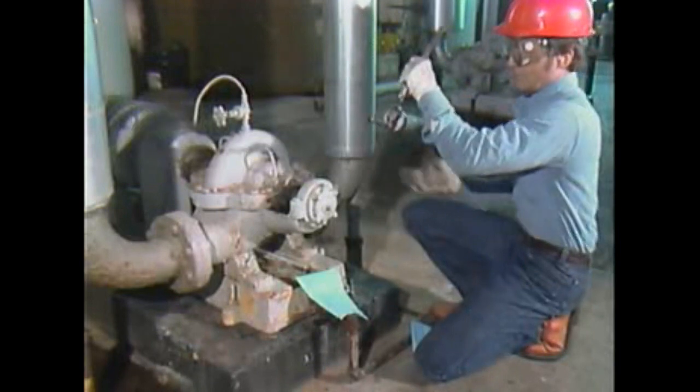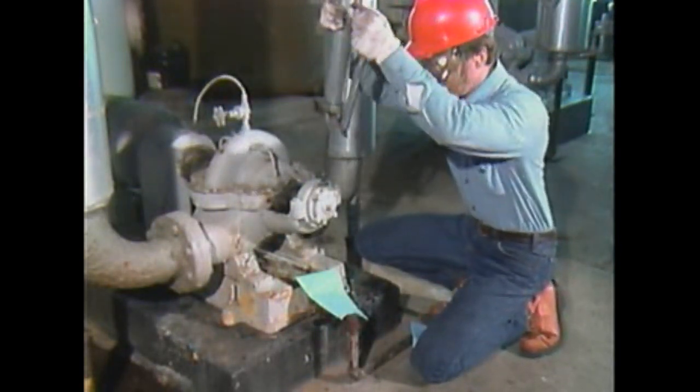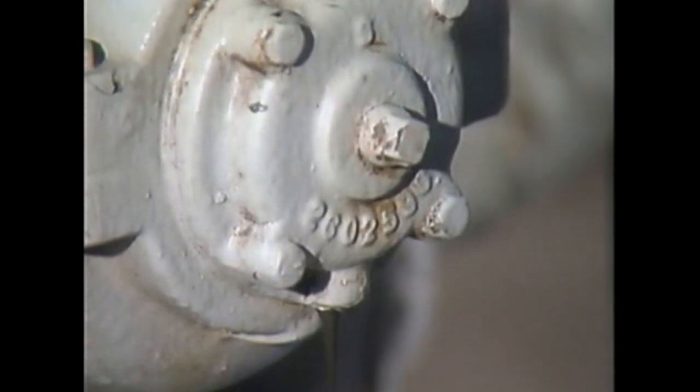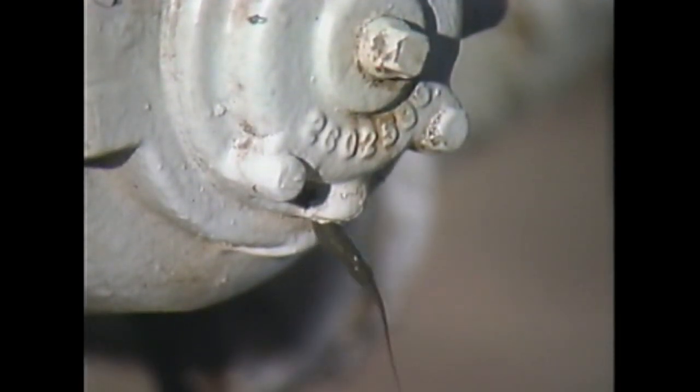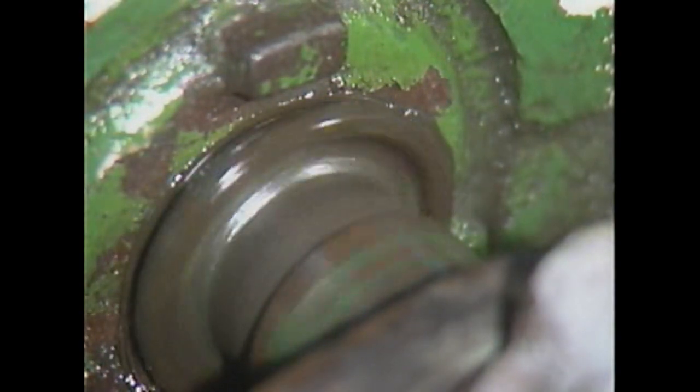A grease's consistency or stiffness is an important physical property for much the same reason as drop point is. If a grease is too hard, it will be difficult to apply. But if it's too soft, it may flow away from where it's needed. Either of these situations could result in inadequate lubrication and damaged equipment.